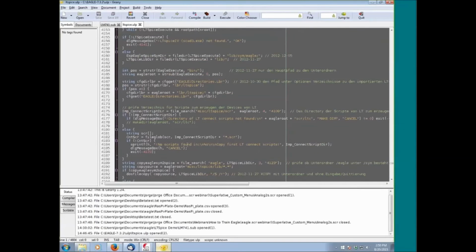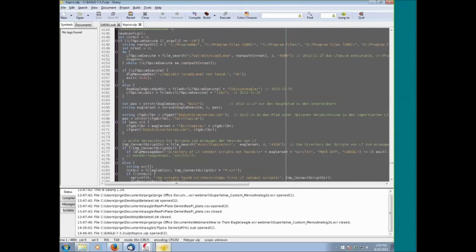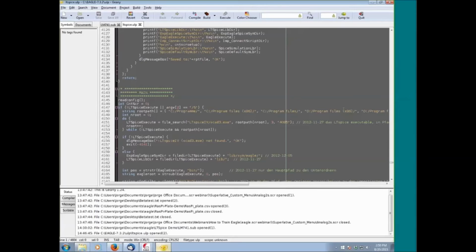If you've installed LTSpice somewhere else, all you have to do is add that root path in here somewhere, basically as another option. I encourage you not to remove any of the old ones. Just tack on another one at the end. When you run the setup, it'll grab it.